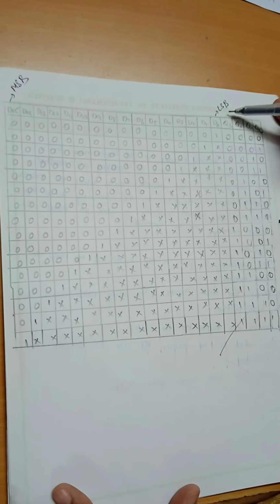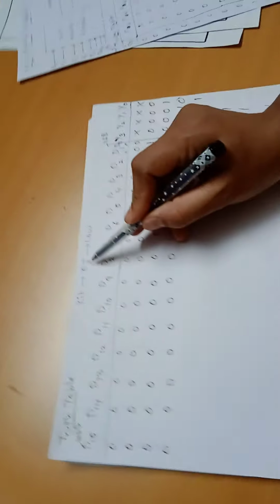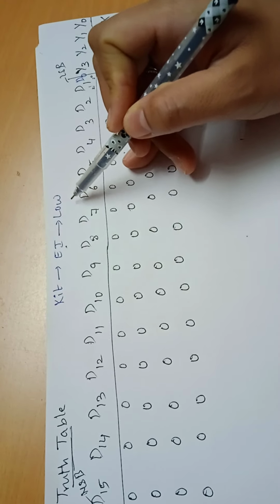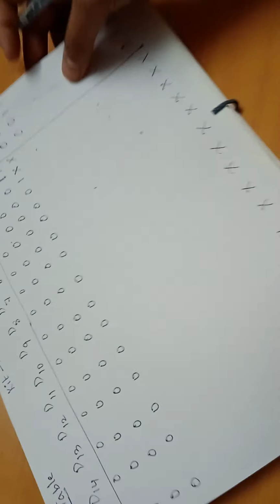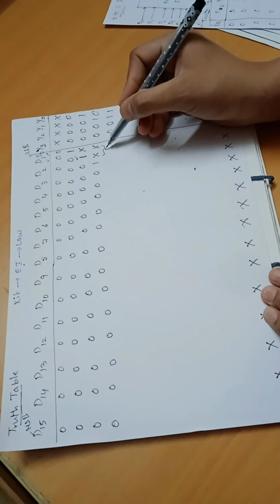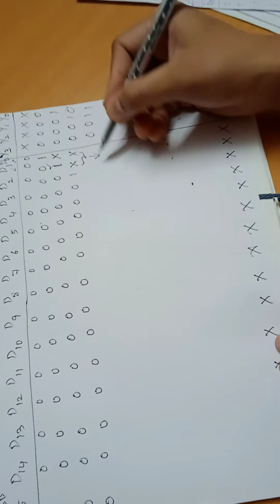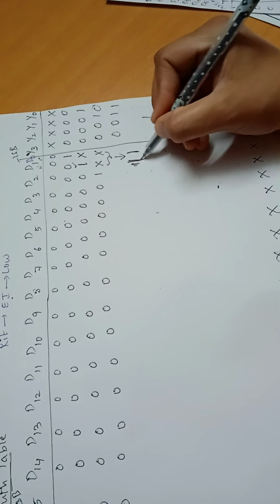You can see this is LSB bit, MSB bit, and outputs here it has been written like Q0 to Q3. Okay, in trainer kit we can see one more pin on the trainer kit, that is enable input. We have to keep it low in order to make this operation successful. And we have a limitation of a trainer kit, like in theory we just see like this is a don't care condition, but in trainer kit if you put this as once, then only we'll get the corresponding output.